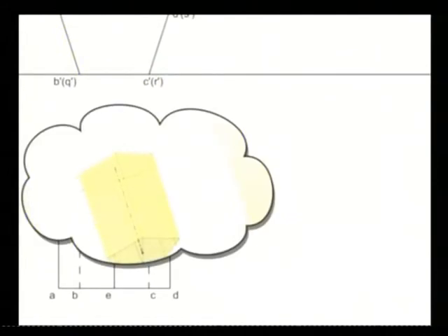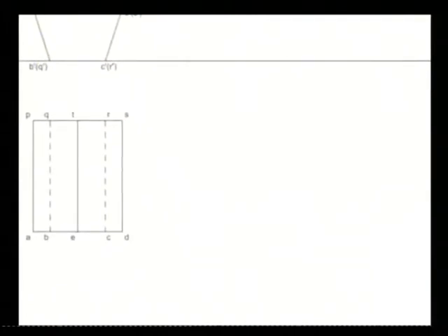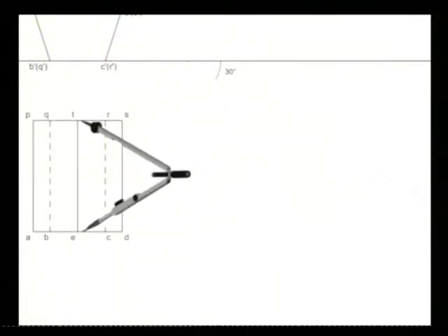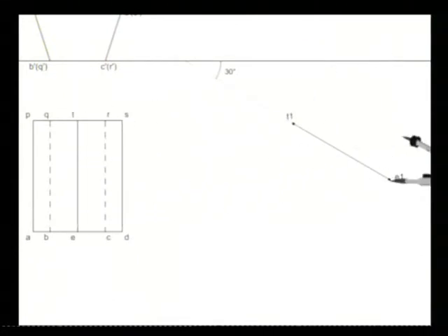Now, it's time to create 30 degrees inclination. For that, draw an inclined line at 30 degrees to XY. It represents the axis of the prism. Copy transformed prism from its top view onto this line.